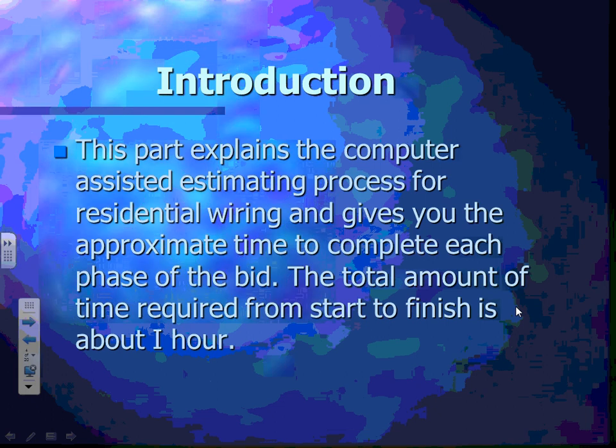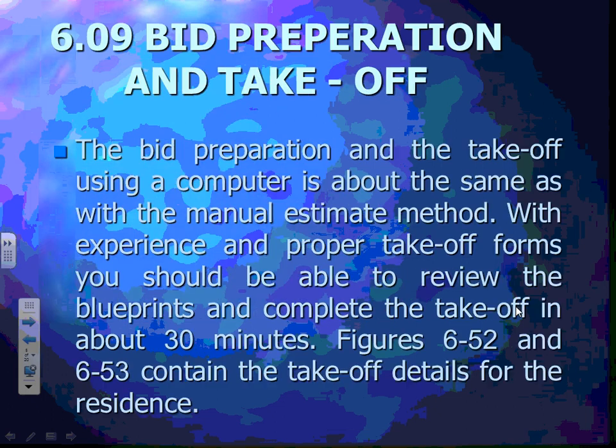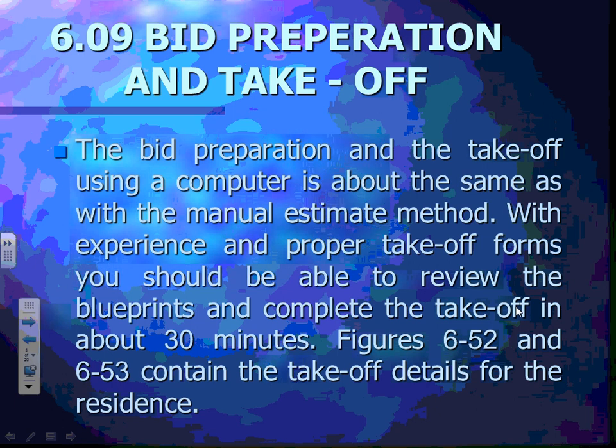So computers, we're going to put all this information, guys, into the computer. Bid preparation and takeoff. We're going to do the takeoff, like I said. You guys are doing this related to different projects, but the project that you did with the takeoff, Adam, I'm going to start with the power, counting all our receptacles in our project in Accubid. We're going to start with the lighting, count all our fixtures, and then start with all your cables and conduits and what not.